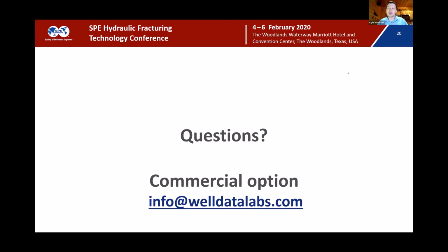So it's a very important QC check for us to know that, because you can imagine if we've got 3-4 wells zippering, sometimes 2 crews going, we need to make sure we can differentiate a new fracture arrival from a wireline pump down. So we can use that magnitude as a very important QC process, but then also additional insight into how many fractures are intersecting that monitor well. Just to be clear, you can today measure that, or that's what you're planning to do in the near future? We can, but I'm confident we haven't squeezed out all the information that's inside of the magnitude.